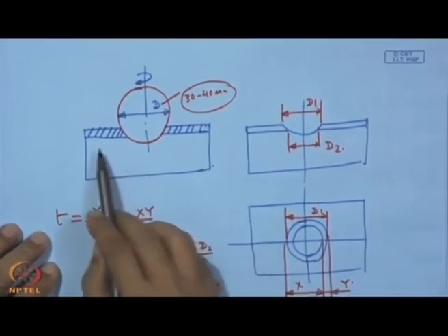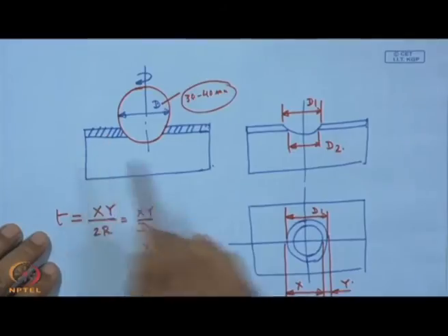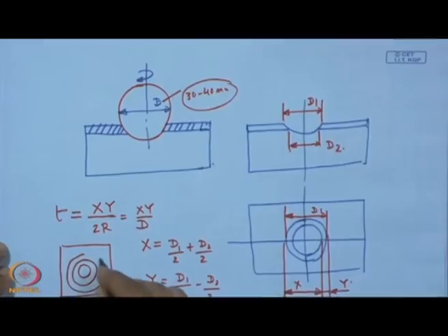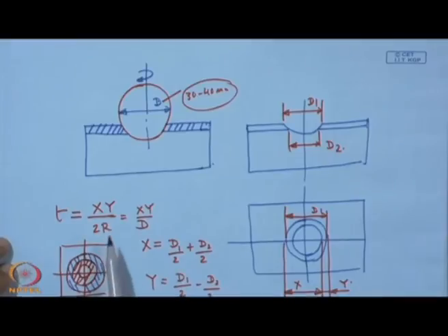Now, instead of a monolayer coating, if we have two distinct layers, a multilayer, in that case also it is possible, instead of 2 circles, to have 3 circles. So, in the central zone the coating is exposed, and we have one coating here and another coating in the outermost ring. From there, by having the respective values of x and y, we can determine the values of T1 and T2 for these two rings.